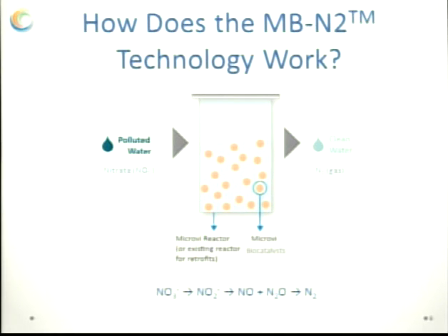So the technology, I think Eugene kind of touched on this, but essentially you would take what we call our biocatalysts that are inoculated, or they essentially have housed billions of organisms inside of them, specific to do a specific job or an application. You can essentially put it inside of a reactor. You can have a packed bed, fluidized bed. So you've got quite a variance when it comes to reactor design. And essentially you've got polluted water going in. It travels through these biocatalysts, it gets degraded, and clean water comes out. Obviously there's a need for an electron donor, and you've got some of CDPH's requirements such as filtration and chlorination that will be needed as well.